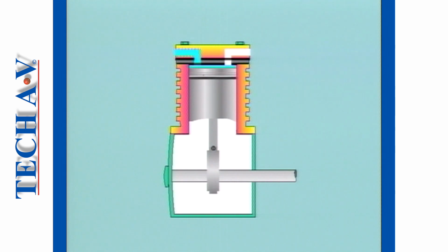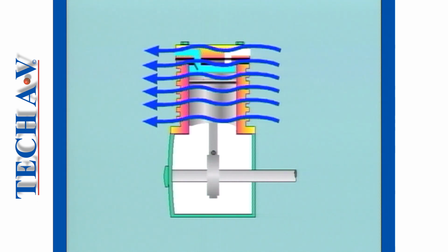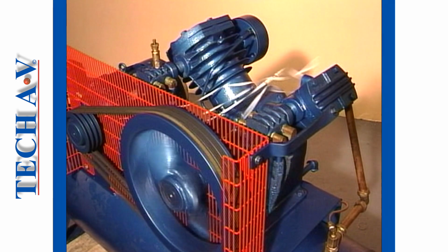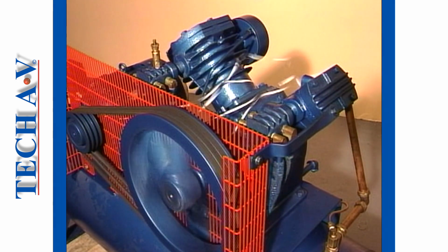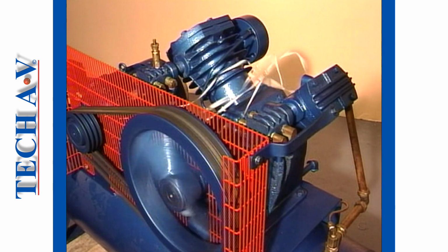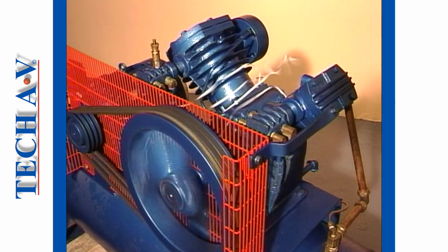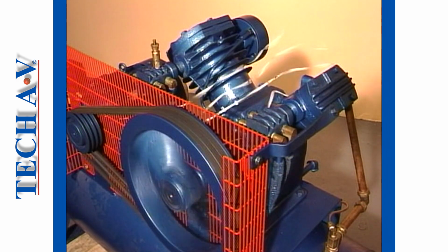To keep the compressor cool enough to operate without seizing up, outside air is caused to blow across the outer surfaces of the hot parts. The flywheel acts as a forced draft fan and directs large quantities of air over the cooling fins. The fins effectively create a large surface area, and this offers better cooling or heat transfer into the atmosphere.